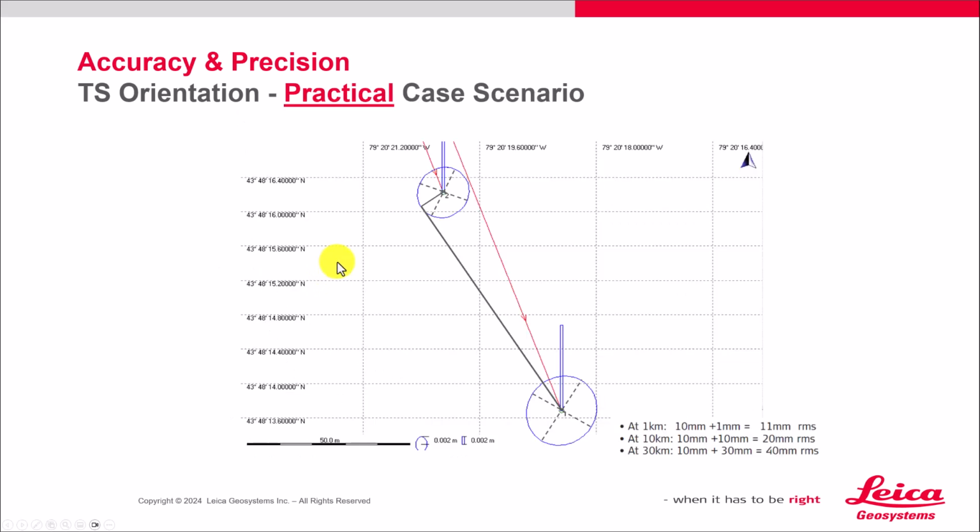I like to come up with the practical scenario, which is where we actually pick this point for a hold of the northing and easting, and we say our backsight is sort of the gospel for our backsight azimuth. If you do that, then at least you're not adding this error back into this one because you're saying it is just the azimuth mark per se.